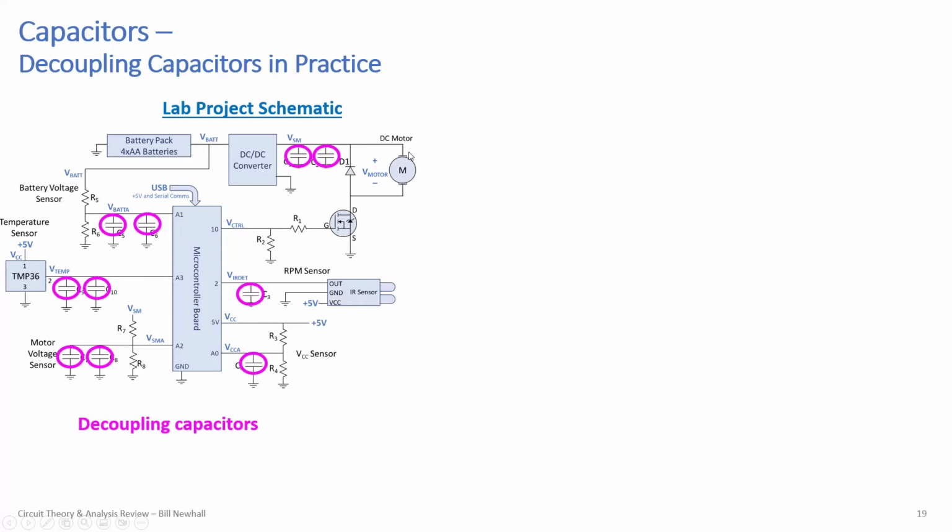And so you have this motor here. Motors are noisy devices, especially brushed motors. Brushed motors, if you remember from Intro to Circuits, they have a commutator and a piece of metal, a brush, that rubs against it, and the current is starting and stopping. That's usually emitting some kind of EM field causing noise throughout the rest of your circuit. And also the start and the stop of the current and the sparking going on inside that motor causes conducted noise too into power supplies and nearby circuits. So these capacitors reduce that noise.